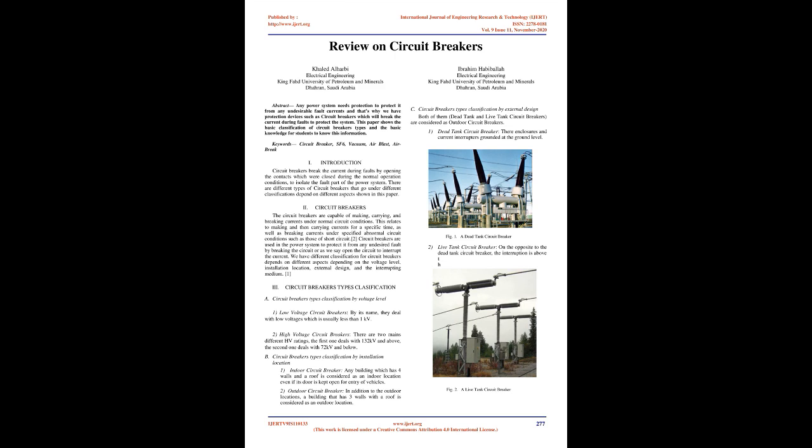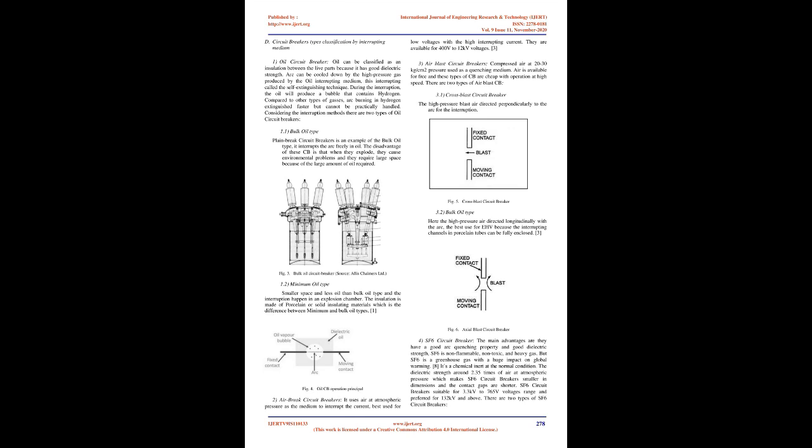C. Circuit breaker types classification by external design. Both of them, dead tank and live tank circuit breakers, are considered outdoor circuit breakers. 1. Dead tank circuit breaker. Their enclosures and current interrupters are grounded at the ground level. 2. Live tank circuit breaker. Opposite to the dead tank circuit breaker, the interruption is above the ground level.